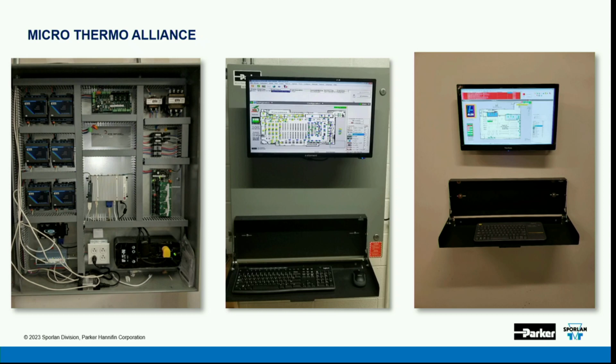I personally, with my old crippled hands, would never trust me to type in all of those alphanumerics because every one of these nodes has its own individual non-repeated alphanumeric identification. That's how we keep things separate in echelon world, right? So the machine does it itself. And being that we're on the subject, if it's a very simple node, it might take 5 minutes to load the configuration. If I have all of the bells and whistles turned on the case controller, it could take 15 minutes.